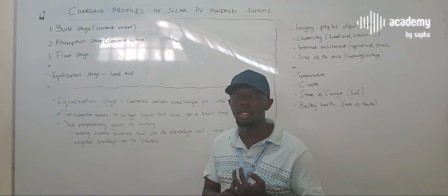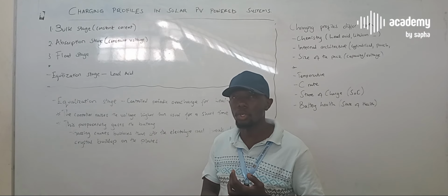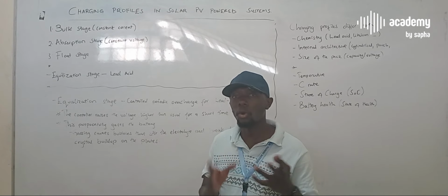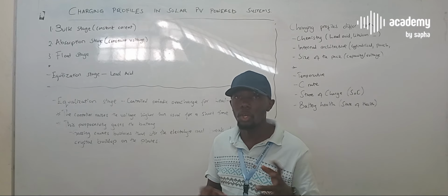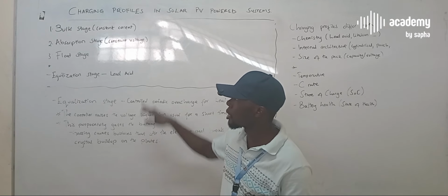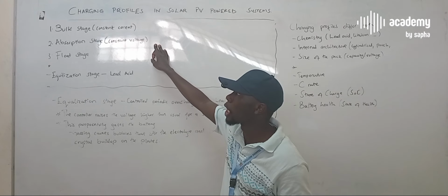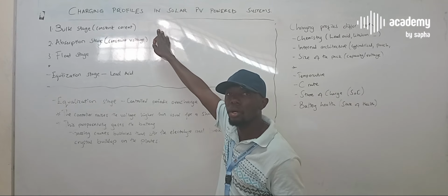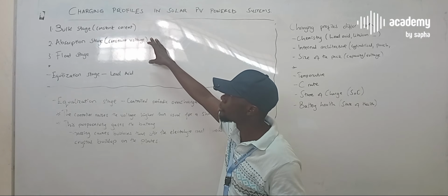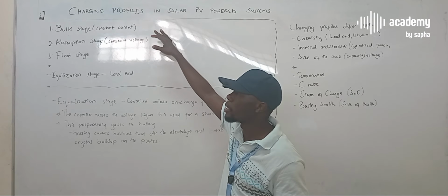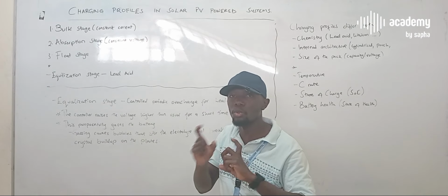And that also means that the charge controller, the inverter, or any other component has to have a proper communication structure between them, so that if, for example, the batteries are at absorption stage and the panels are capable of releasing bulk stage, the inverter can pick the absorption stage voltage, and then the extra can be sent to the loads directly. So those little bits of communication.